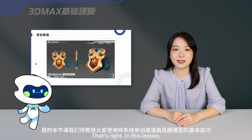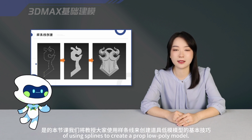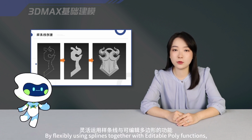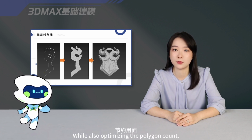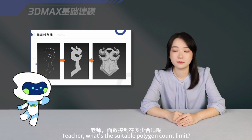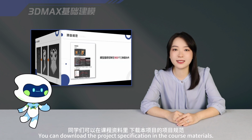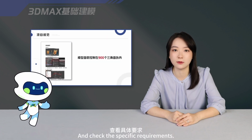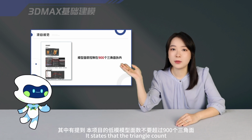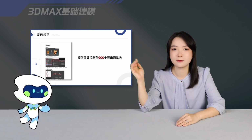That's right. In this lesson, we will teach you the basic technique of using splines to create a prop low poly model. By flexibly using splines together with editable poly functions, we can maintain the form of the prop low poly model, while also optimizing the polygon count. Teacher, what's the suitable polygon count limit? You can download the project specification in the course materials and check the specific requirements. It states that the triangle count for this project's low poly model should not exceed 900 triangles.